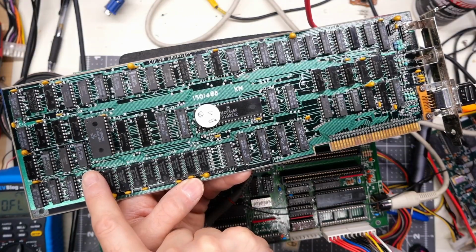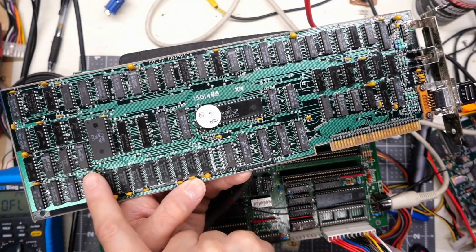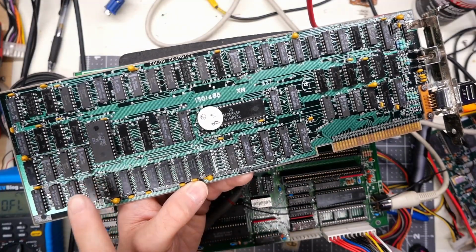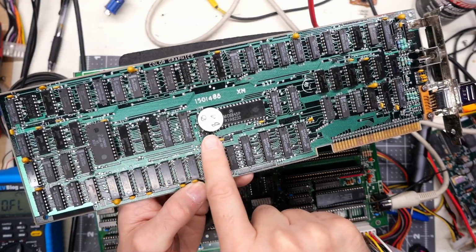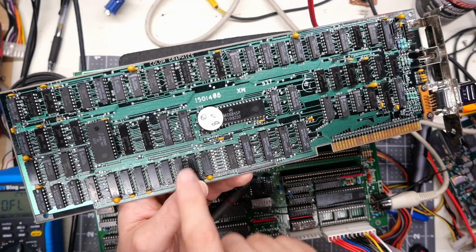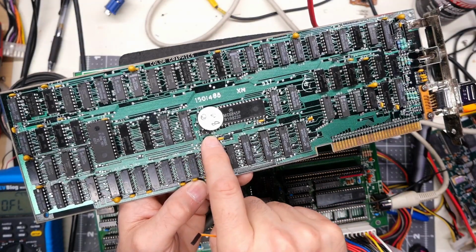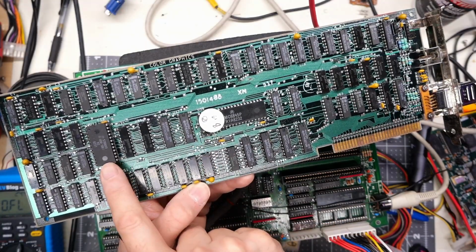So remember how I installed an extra pin over here? The reason why I did that is this pin is connected to the flashing circuit. So when the attribute bit is set for flashing text, this pin changes. Well, this thing here, when you put a jumper on it, basically grounds this pin on the left. The pin on the left is pulled up to 5 volts, and that goes to the address line on the ROM chip. Well, when you ground that, basically you get the thin font.